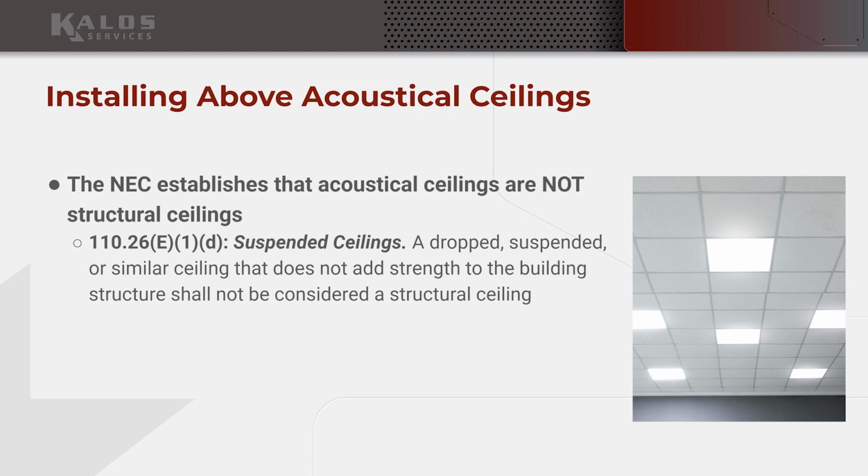And so long as the ventilation is okay, so like if there were insulation up there, you couldn't sit it in the insulation. You would still have to observe all the required ventilation and clearance requirements for that transformer. But transformers are not required in many instances to be readily accessible. They're only required to be accessible. That's a code distinction that we can get into in a future class, but it basically means you can reach it with a ladder. Tools are allowed to be used to get to it. It doesn't have to be readily accessible.